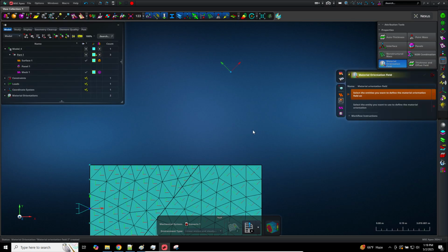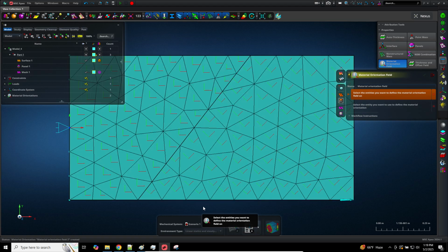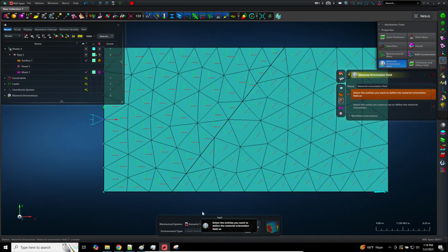So when I go back here, all the material coordinate systems are now parallel to each other. They're all aligned to each other. Now what I'm doing here is I purposely have different 0 degree directions, if you will. The material coordinate systems are different. This one's running horizontally here on the left, but here on the right, it's at an angle, if you will.